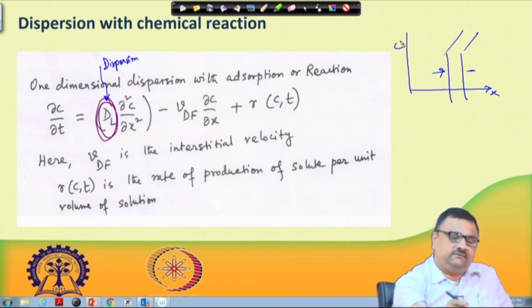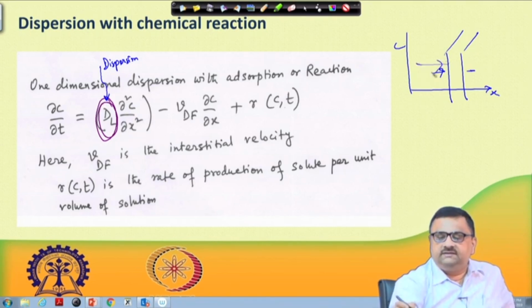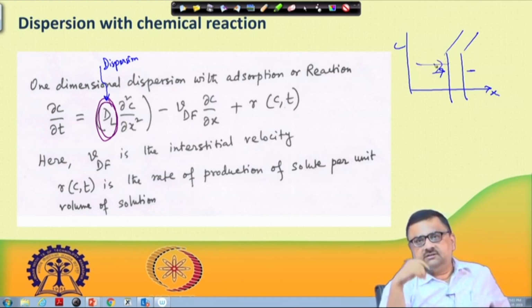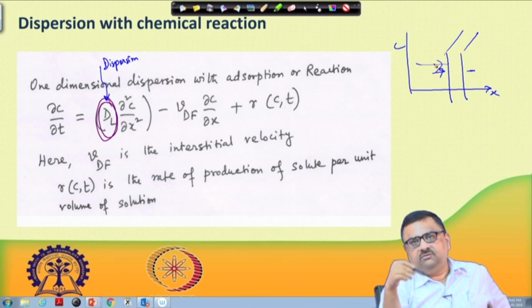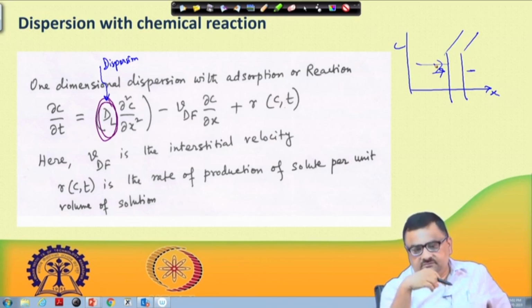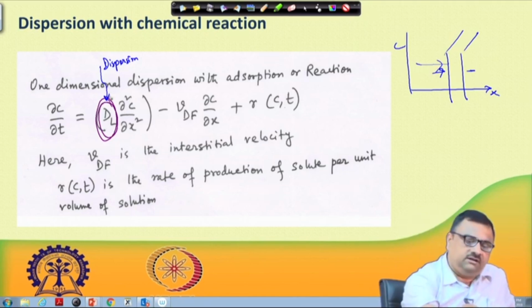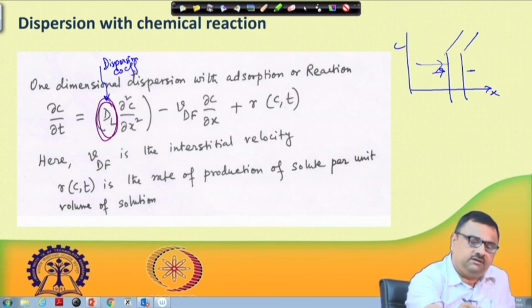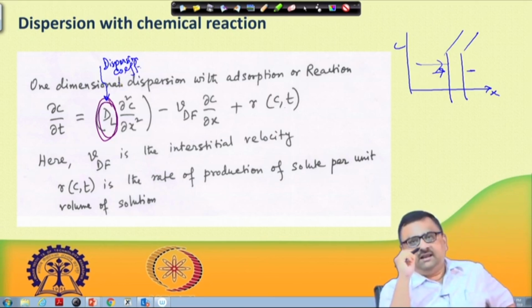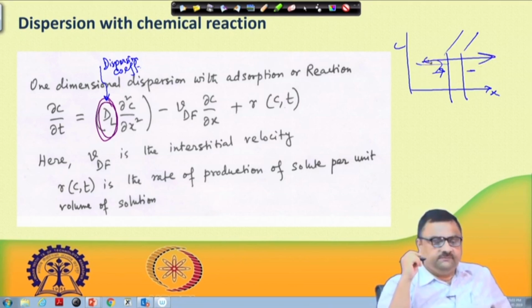Here we are directly saying that there is a flow taking place. So, this is not going to be pure diffusion. So, let us directly put this as a dispersion coefficient. That means this accounts for both diffusion and the effect of velocity, and because of that there is smearing of the front, so all those are included. So, instead of diffusion coefficient, now we are talking about dispersion coefficient, given the name DL, and since we are looking at dispersion in this direction, we are calling this longitudinal dispersion.